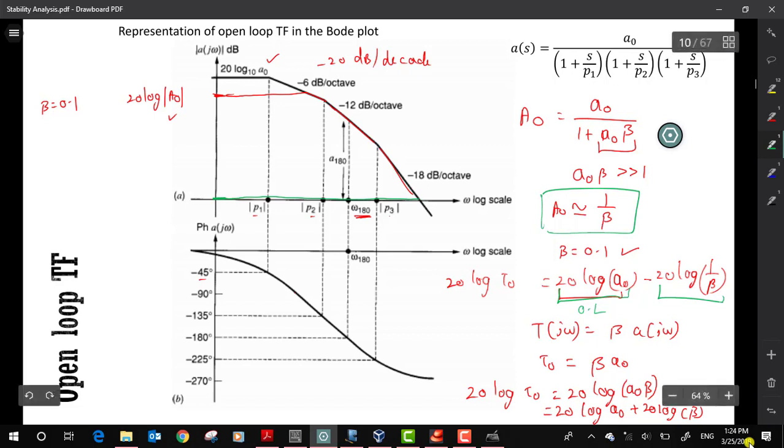So I have a closed loop DC gain magnitude. If I want to extract the loop gain, I need to subtract the closed loop magnitude plot from the open loop magnitude plot. So what I'm really stating is that this particular portion gives me the loop gain expression, or the plot of my loop gain. Is that making sense? Are you clear with it?